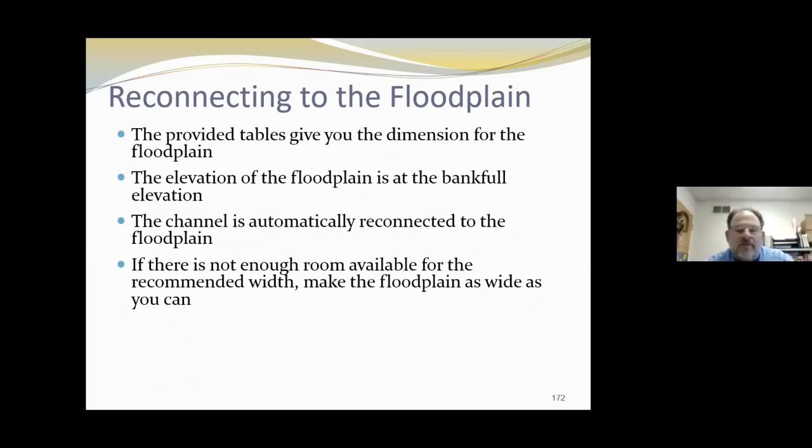Yeah, so generally speaking, on that slide we had a while ago where it showed a 100-year floodplain and a 25-year floodplain and then bank full, we're not talking about 25-year event floodplains or the 100-year event floodplain. We're talking about the floodplain that's needed at that bank full height so that channel can get out, spread out, and get its energy knocked out so it's not erosive. That's a good point, Mike.